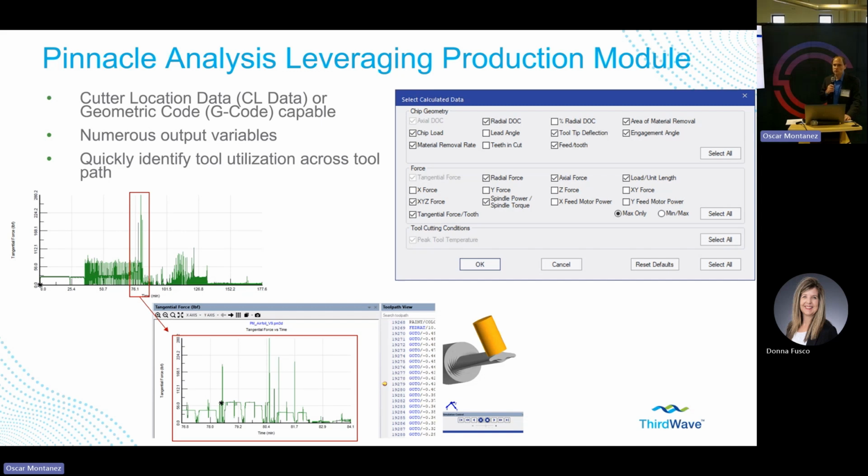But how easy it is to identify, is your toolpath good? So you can run my virtual machine, you can look at verifying the toolpath, and it'll tell you if you're going to crash the machine or not. Here it'll tell you if you have a point where the tool is coming back in contact, whether it's rapid or just rubbing against the part. You can see that force spike there. And that's exactly what was happening.